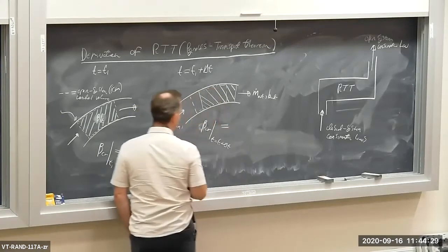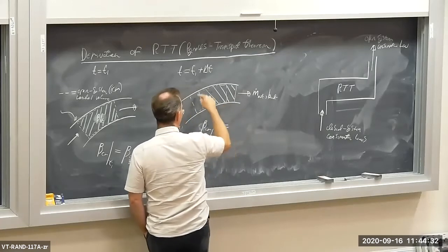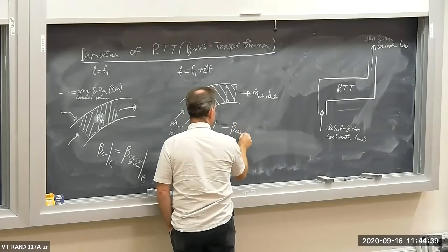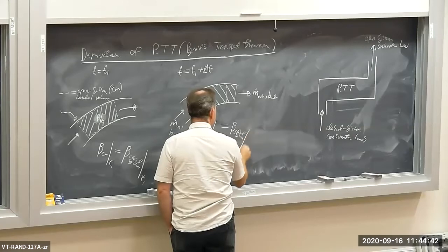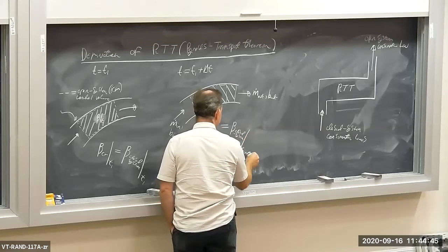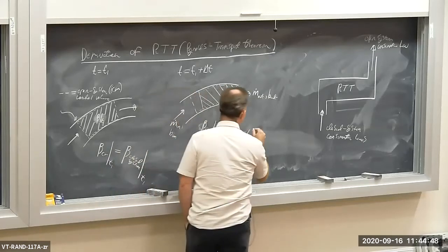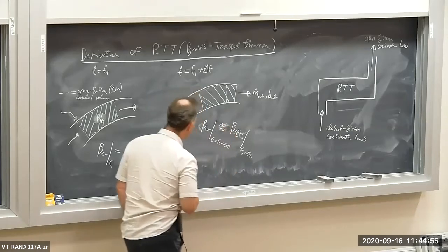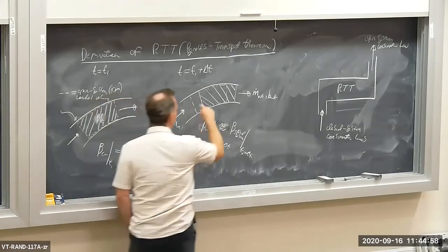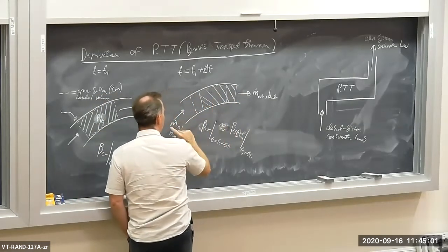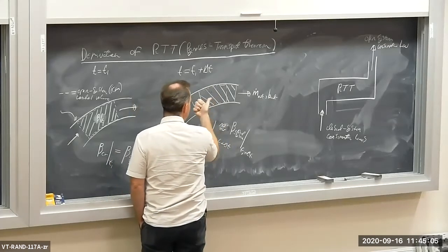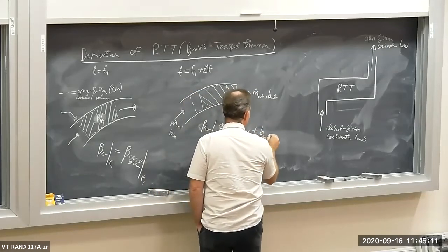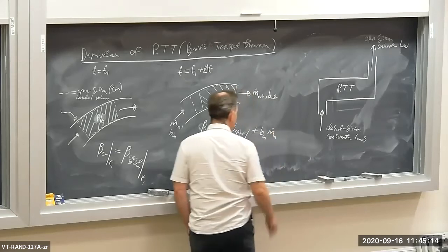well, that's going to be equal to the amount of beta in my closed system. So beta in the closed system at t1 plus delta t. I should make this approximately equal to. These are estimates. The amount of beta within the control volume is approximately equal to the amount of beta in my closed system, plus the amount of beta that is flown in across my control volume boundary. So plus B in m dot in